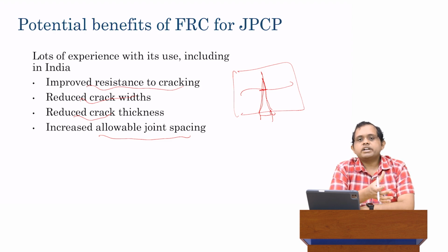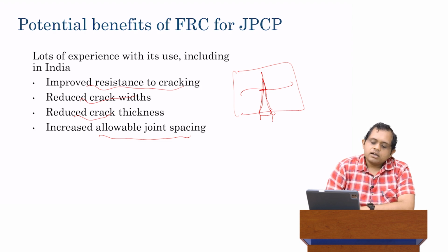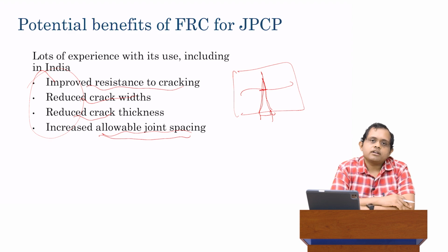So although it is true that addition of these fibers obviously is going to cost money, so there's a slight economic cost to this, the economic cost can more than be made up by the fact that you could increase the joint spacing, as well as these other benefits which you get relative to performance.